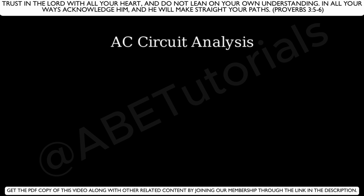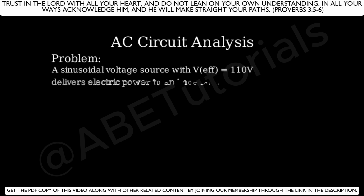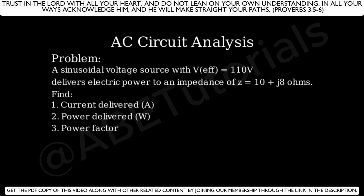Today we're going to solve a problem involving AC circuits and complex impedance. Here's our problem. A sinusoidal voltage source with V effective of 110 volts delivers electric power to an impedance of Z equals 10 plus J8 ohms. We need to find the current delivered, the power delivered, and the power factor.